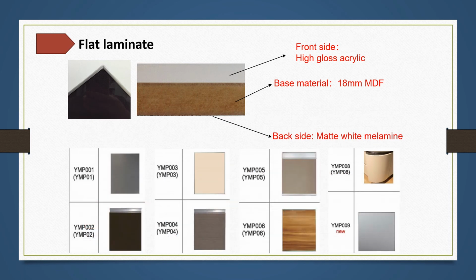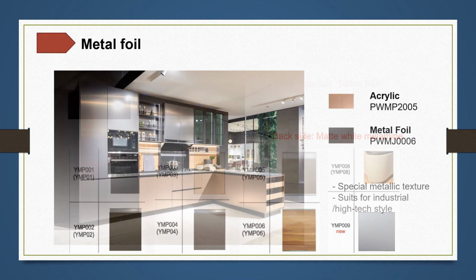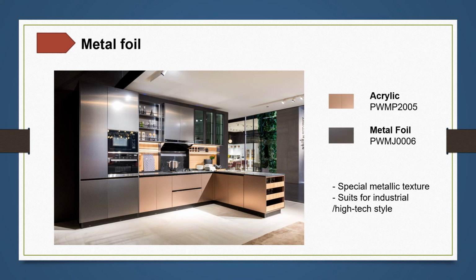For solid wood products, since they are more natural panels, there are a couple of limits that come with the raw materials. For example, a door style for solid wood is usually a one-to-one match with a specific type of solid wood, because even if you use the same paints on different solid woods, you get different final colors. So to ensure the credibility of the pictures, most solid wood door styles are a one-to-one match with the solid woods, sometimes 1-to-2. Also, same as with the PP materials, solid woods are in frame structures, and sometimes when the overall size is too small, and for some special door styles, the core of the door panels will be MDF coated with wood veneers. So that's the basic knowledge for the paints. And now let's take a look at a couple of lacquer sample kitchens and solid wood sample kitchens.